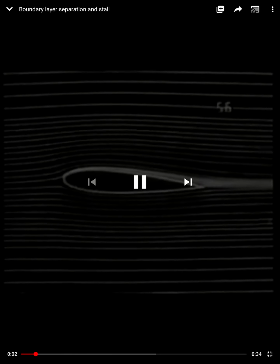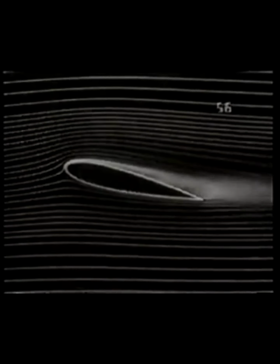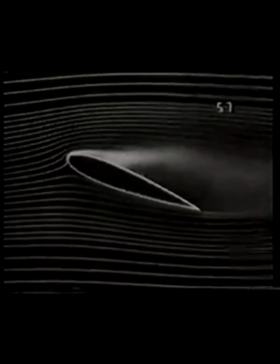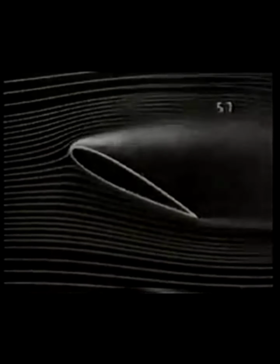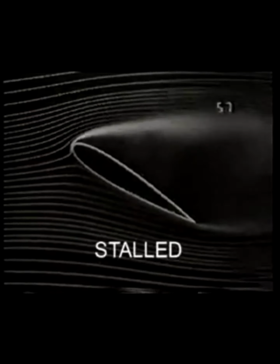transition. As the angle of attack of an airfoil increases, the flow in the boundary layer stops, then reverses direction. This is called boundary layer separation. As angle of attack increases further, the point of separation moves forward on the airfoil until it has so disturbed the flow around the airfoil that further increases in angle of attack produce less rather than more lift. In this condition, the wing is said to be stalled.